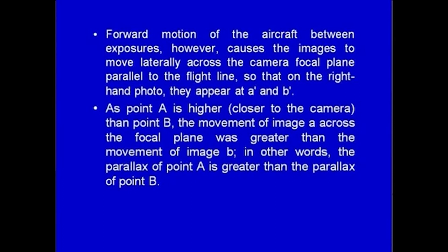As point A is higher, that is closer to the camera than point B, the movement of the image across the focal plane is greater. The movement of the image a, in other words, the parallax of point A, is greater than the parallax of point B.